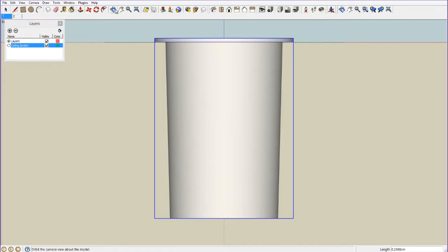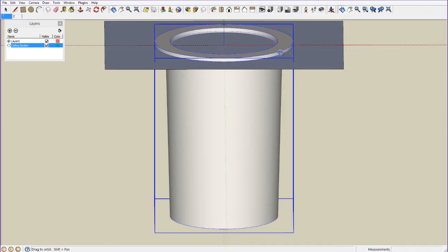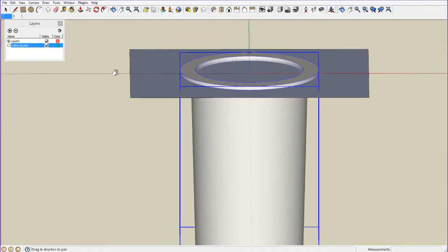So now when we look back, the trim is clear of the ceiling, but you will notice straight away that there's another item here, which is that the ceiling plane is going to cut off the view of the internal of the downlight here, and also quite possibly cutting off or blocking the light output from the photometric file.